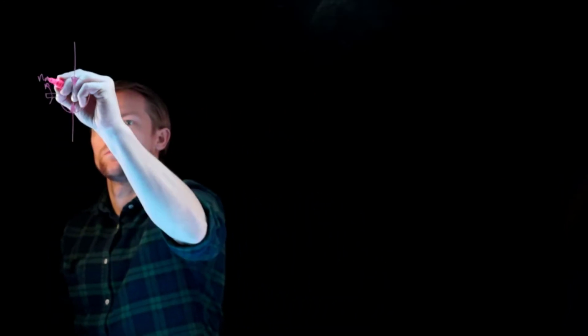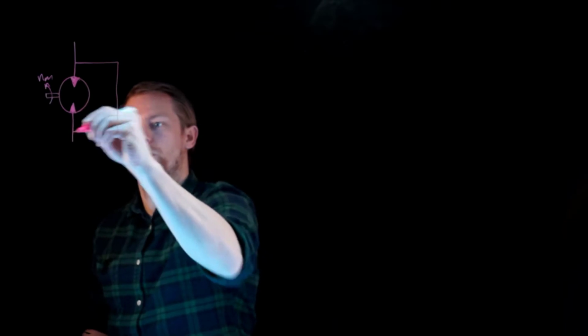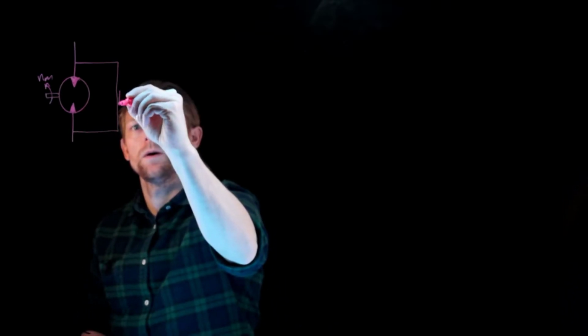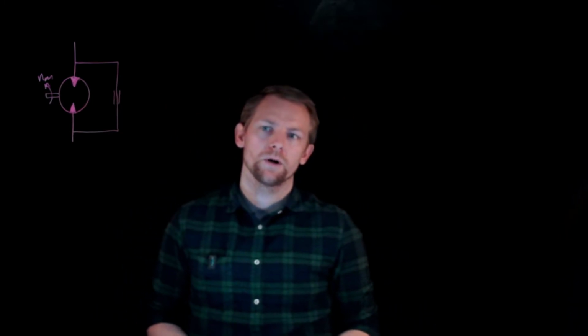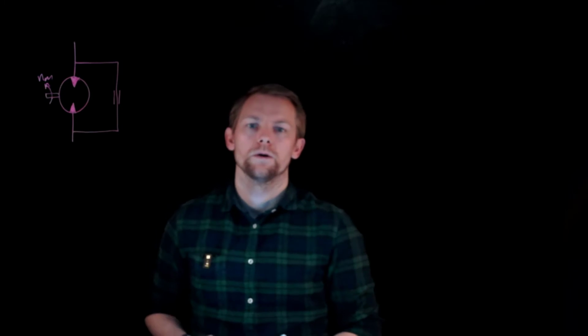So let's put up a sketch. Here we have our motor. And when we run it, it has some rotational velocity. And to include the leakage part, what I will do is to add this parallel path here and illustrate like this, that is not an orifice that I'm modeling, but a laminar orifice, you could say. But it's a laminar flow that I'm modeling in parallel with the motor.